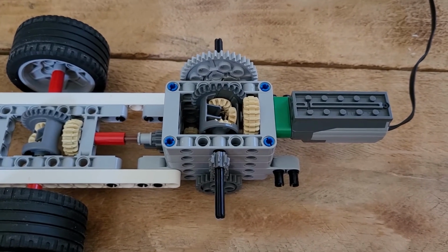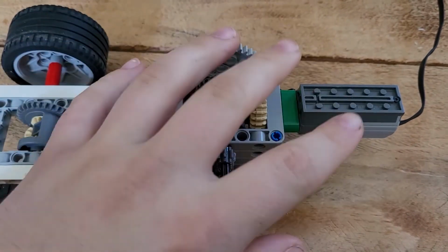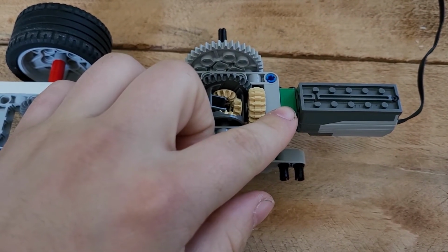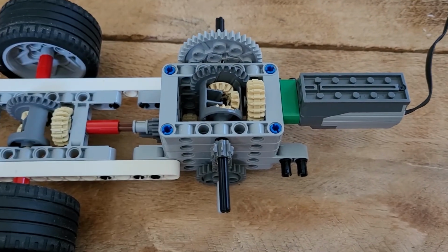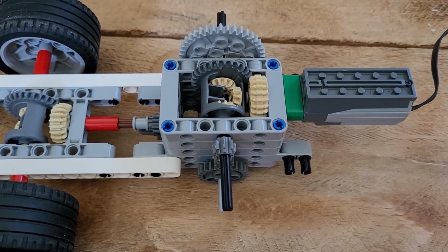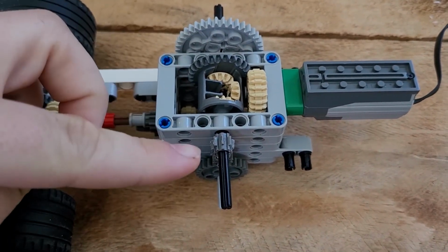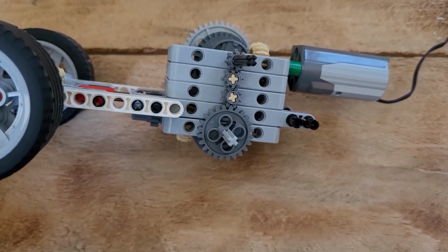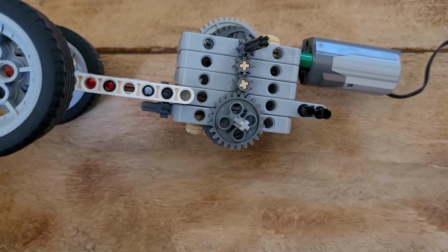So the way that this automatic transmission works is quite simple. We have it driven right here by this continuous speed electric motor, which goes into this first differential here, which, if you know a differential, it kind of follows the path of least resistance like water. So we have output to the larger gear and then output to the smaller gear. Following the front side here, we just have a series of 1-to-1 ratios until we hit that larger gear.